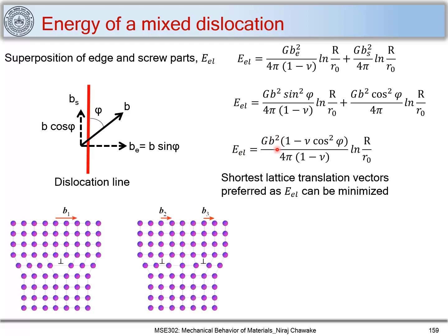Now let's look at this example where you have a Burgers vector, and you can see that the Burgers vector magnitude is b1, and here is an edge dislocation which we have shown. So here you can see there are two extra half planes, and this scenario can be possible in case of an edge dislocation present in ionic crystals. And this b1 can be dissociated into b2 and b3 in this way, which we have shown. This dissociation of b1 into b2 and b3 can only be feasible with certain criteria, and let's look at those.